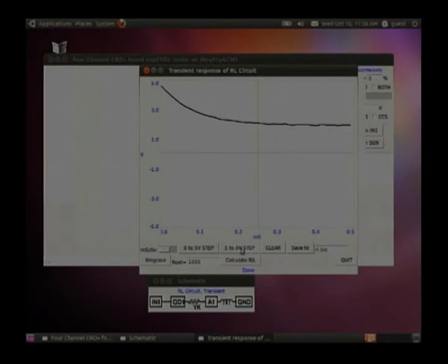That means we are keeping the point OD1 at 5 volt and suddenly taking it to 0. This gives a very interesting result. We gave a step here, say 5 to 0 volt, but the voltage across the inductor suddenly went to something like -3. We did not apply a negative voltage, but it went there, so that it generated a negative voltage. This is due to the phenomenon called back EMF, and after that it starts discharging through the resistor, and you have this discharge curve like this.